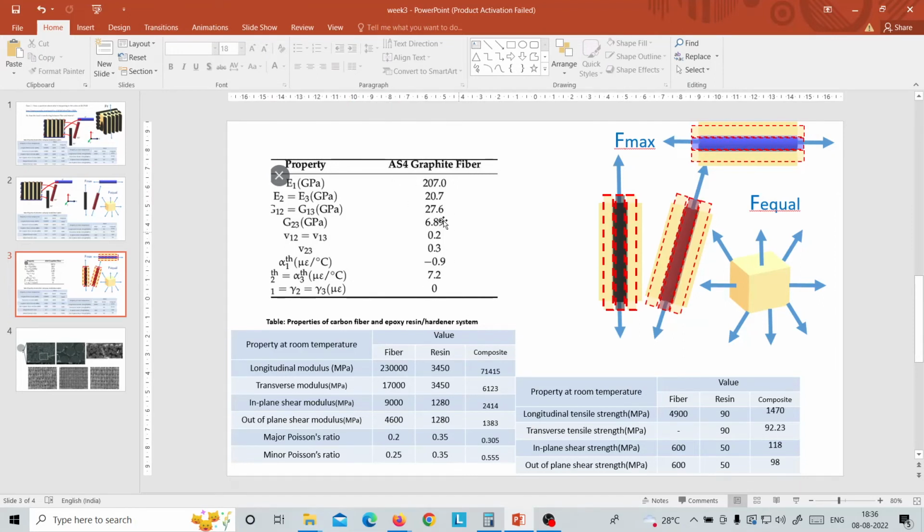But from this example, application-orientation wise, if we want to choose between graphite fiber and carbon fiber, for applications which only involve force application in one direction, like making a pillar out of this composite and placing something over it, or making a bridge structure, a straight chain with tensile loads in both directions, you will choose carbon fiber because its longitudinal modulus is higher.